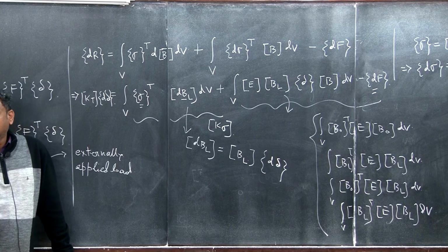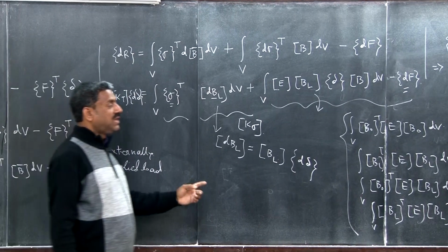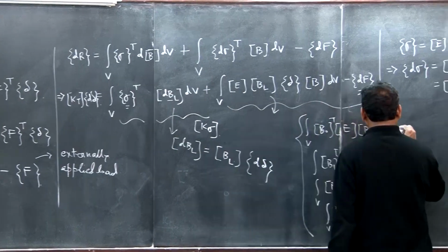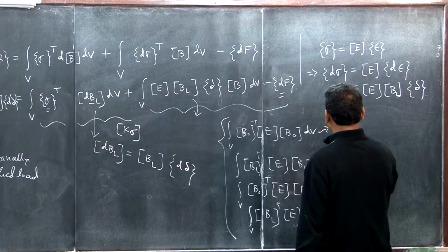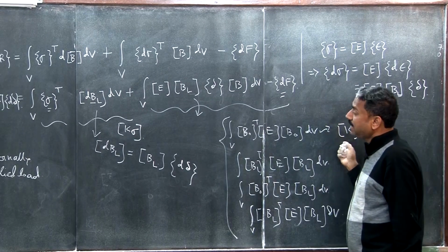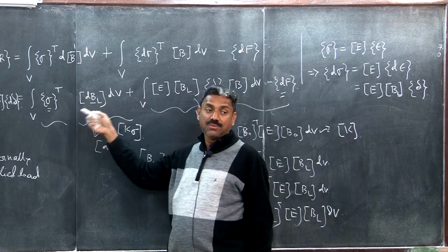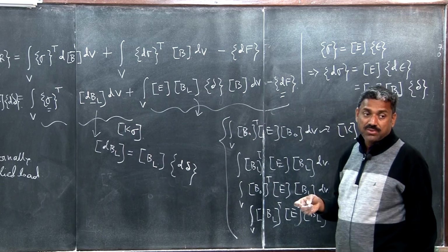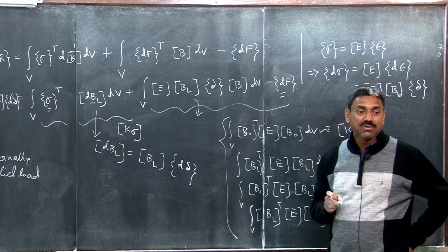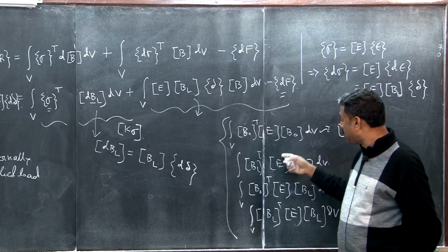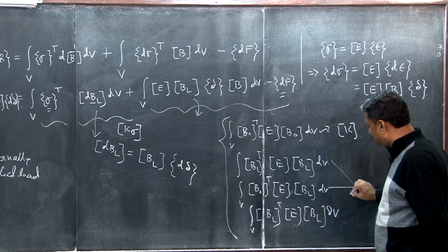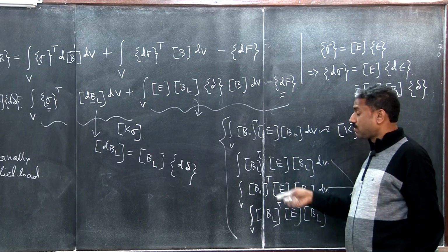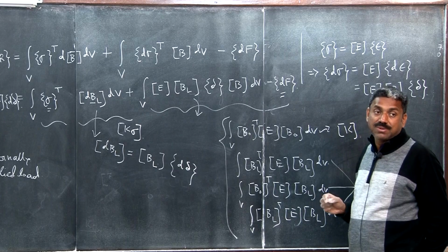Okay. So do you see how the linearization is done? When you are doing the linearization, only this part will be there. See, this part is the linear stiffness matrix. So K plus K sigma will be equal to 0. If there is no externally applied load, dF is 0. So that becomes the linearized stability analysis, and we neglect this part. These are nothing but nonlinear terms, which otherwise need to be included for a nonlinear stability analysis.